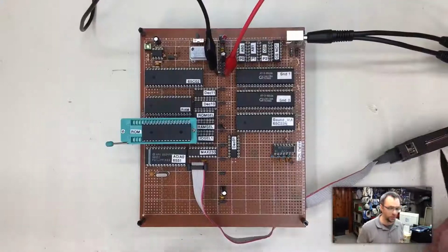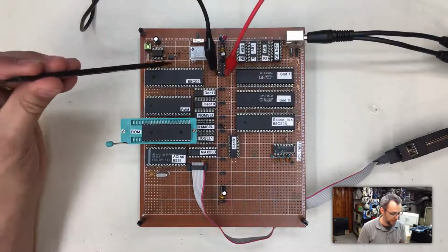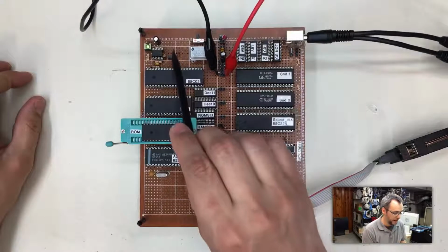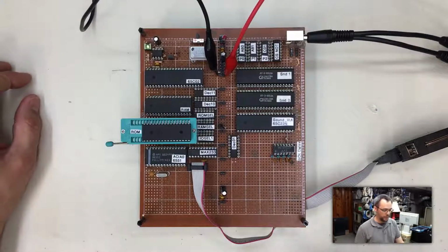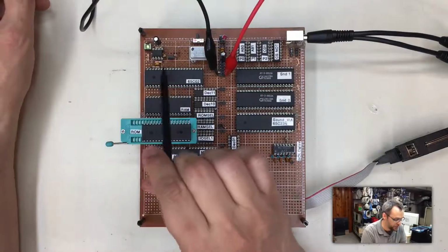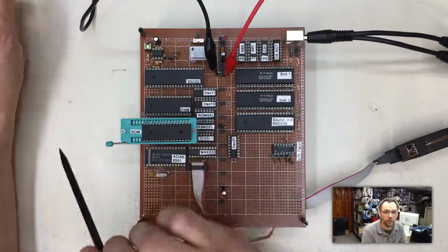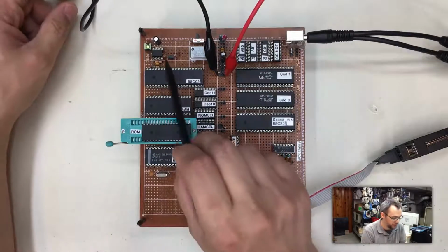Let's get into some hardware changes on the machine. One of the biggest hardware changes to start off with is right up in this area here. As you'll notice, that hex inverter is gone, and I mentioned this on one of the previous episodes. I was thinking about removing that hex inverter and replacing it with just a simple transistor inverter, and I did that, and it works just fine.